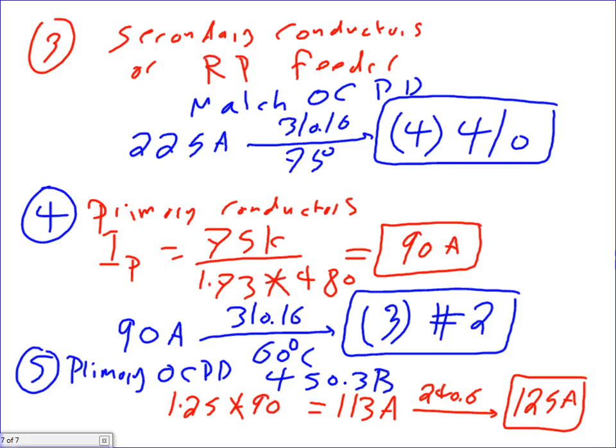That's his question about the taps: how long can they be? It explains it pretty well in 240, section C, transformer secondary conductors, where they can be protected by the primary. There are all kinds of different scenarios, where they can be and how long they can be.